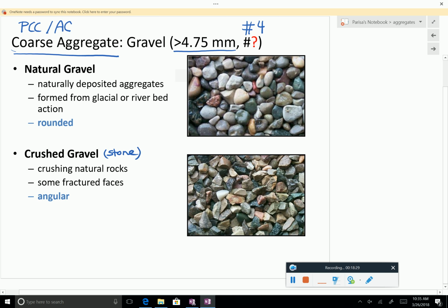So that means that you all know what a sieve is, no matter what you are taking, soil mechanics or not. The size of the sieve kind of determines the number. We'll talk about it. And if it stays on the sieve size number 4, which has the size 4.75 millimeter, like kind of a square, then it's considered coarse aggregate for concrete mix and asphalt mix design. And the shape is pretty much defined by the source of the aggregates, as you talked about.